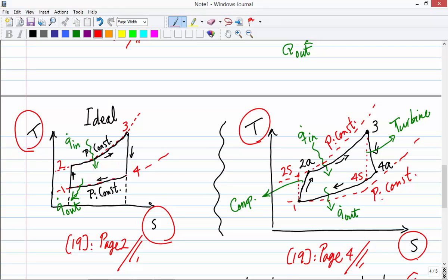Determine the mass flow rate of air through the cycle. Important note: account for the variation of specific heats with temperature, which means that you can assume air is an ideal gas, but when you are talking about enthalpies in the process as temperature changes, you cannot say delta H equals Cp times delta T. Why?